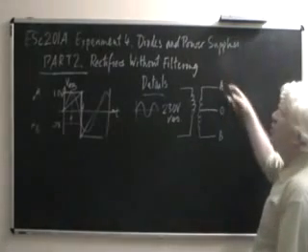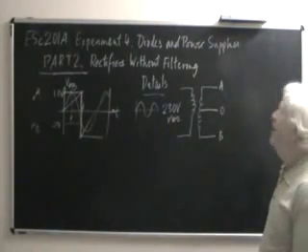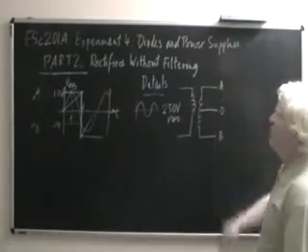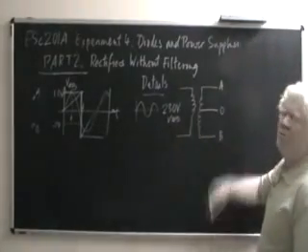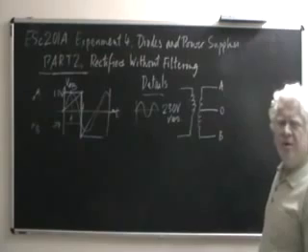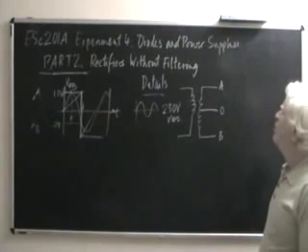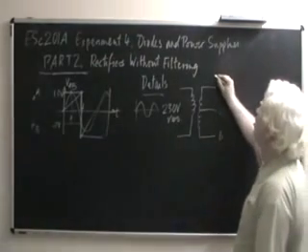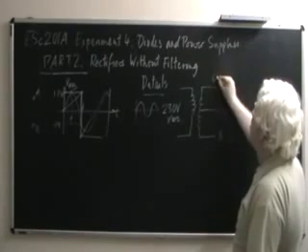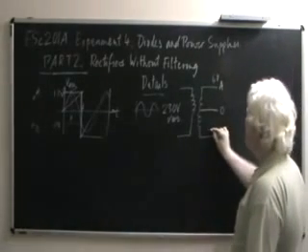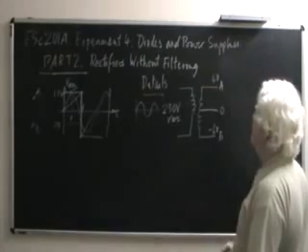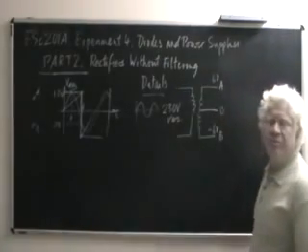So, you can choose to ground any point you like. But the main purpose of this transformer is to step down 230 volts to approximately 1/10 of that value. In fact, 1/20th of that value, so that you get around 6 volts here, minus 6 volts here, with respect to the 0.